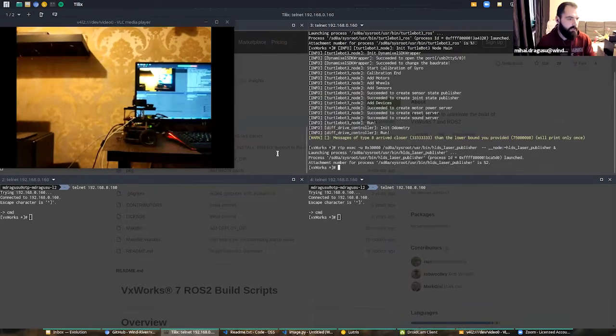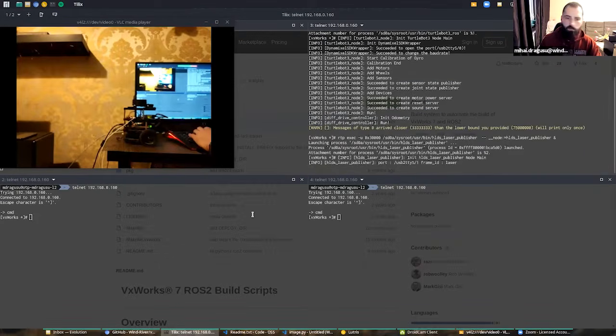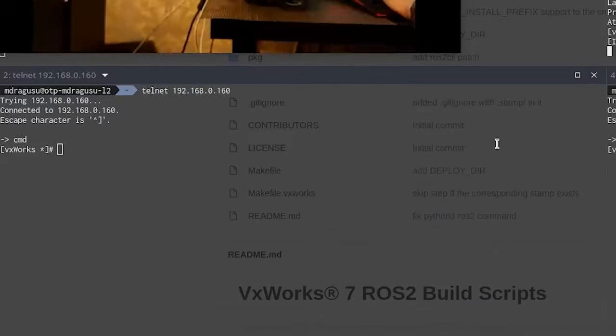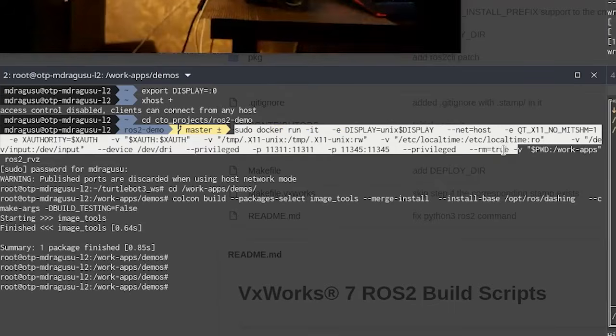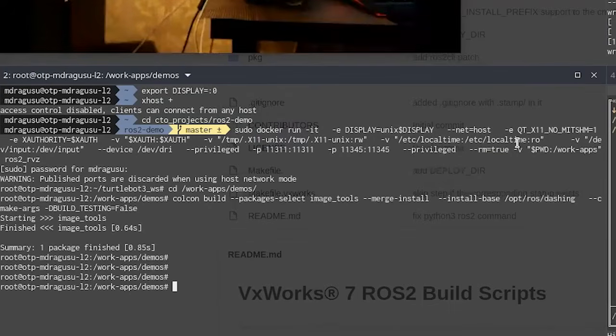So with that done, if your robot is connected to the same network as your development setup, on the Linux side of things, where you would have a ROS2 setup already done, you can see the topics. That's what they call them, basically what the robot publishes over the network.